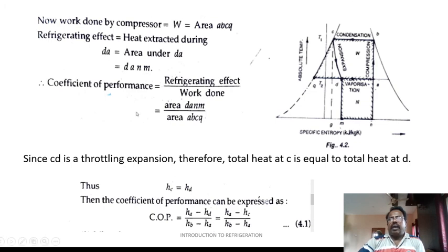So we are considering this, that is, we are studying this temperature entropy diagram on the wet, supersaturated vapor and dry saturated vapor regions, because in order to have good efficient performance of the refrigerating machine, the vapor after compression is required to be a dry vapor.